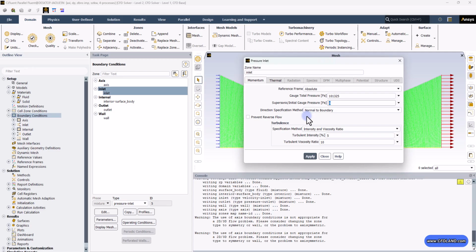I want to put 98,000 Pascal for this. This is the static pressure right at the inlet face, this boundary in blue color. And there are just two main reasons that we're doing so. First, it is the driving force. The air moves because of the difference between total pressure and static pressure. The gap between 1 atmosphere and 98,000 determines how fast the air enters the nozzle.